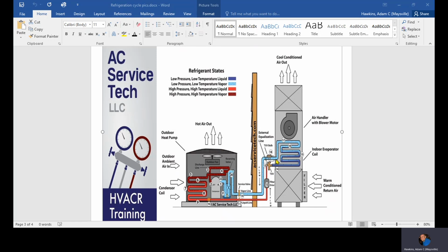Inside, the colder thing was the coil itself, the refrigerant. Outside, the colder thing is what? It's the air, right? So if it's 95 degrees outside, you may think, well, that's really hot. Well, remember what I told you. Everything is relative. Even if we think 95 degrees is hot, 95 degrees is cool when we compare it to 120, right? So if we get that refrigerant temp up to 120, and the air coming across it is 95, where's the heat going to go? Heat's going to go with the colder thing.